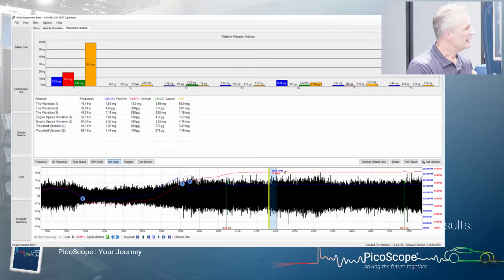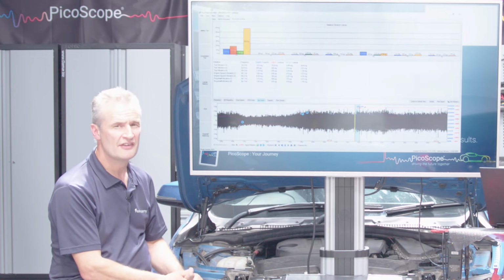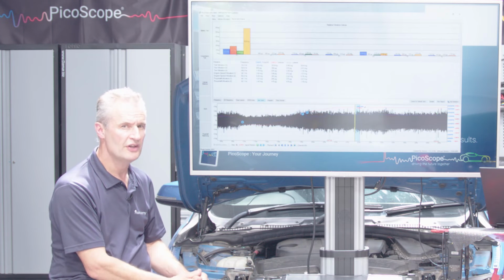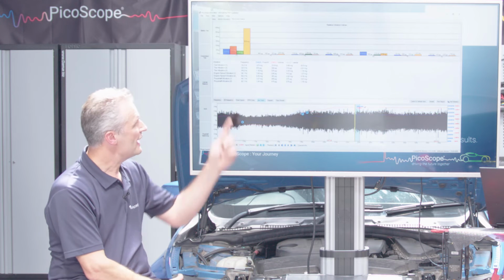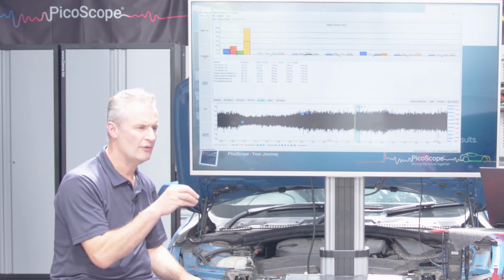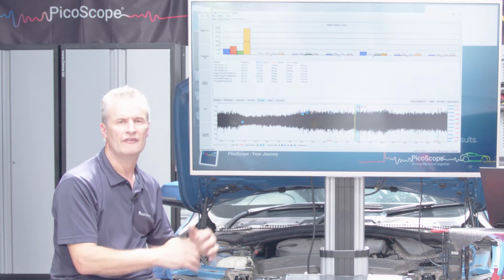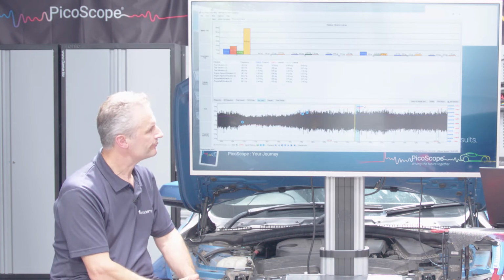We'd also gave a little tip that the DTI gauge placed on the drive shaft highlighted our out of round or our run out on the shaft, in which case it will generate 1 disturbance per revolution of the wheel. So a very easy trap to fall into, that it's a T1, but actually yes, it is T1, a component rotating at tyre frequency but not a tyre, and the amplitude is the giveaway that we are now above, or we've zoned in on the epicenter of the vibration.